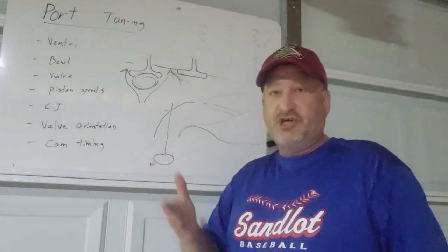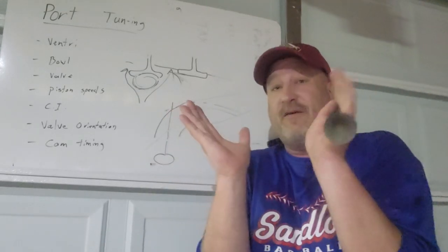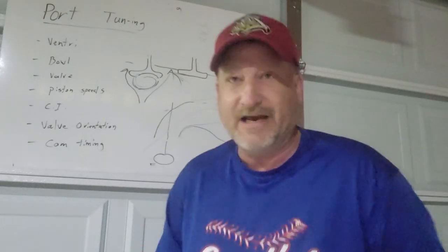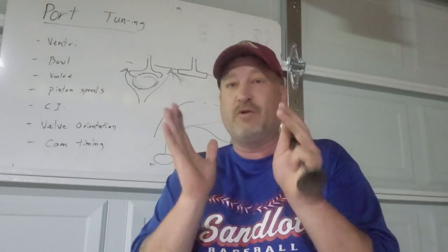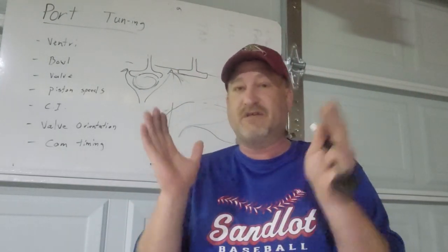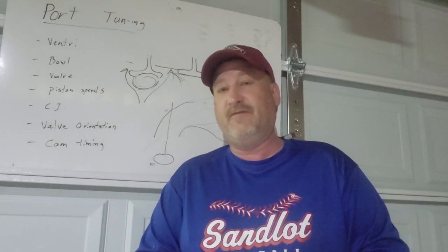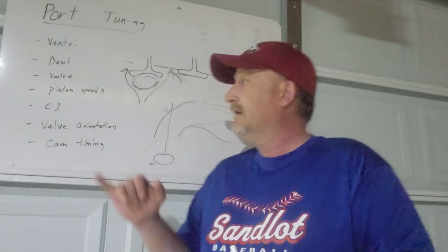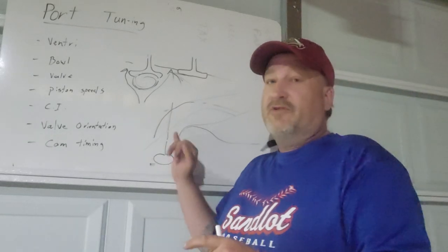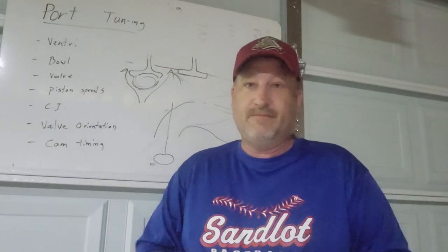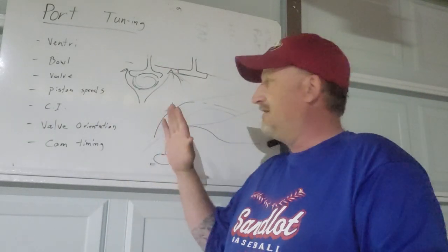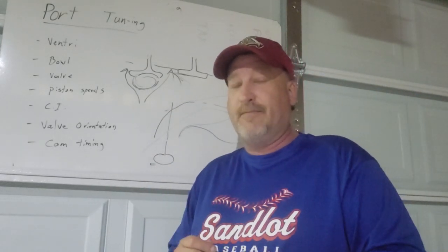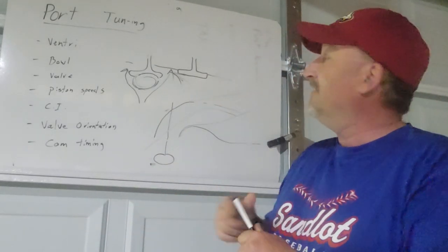And that's also in conjunction to the angle of the banks of the engine. Okay, so for you Harley guys out there, it's the difference between the V of the Harley Davidson compared to the angle of the typical V8 engine. That alters port tuning. But between the Chrysler, Ford, and Chevy, the original engineers behind those combinations were looking for